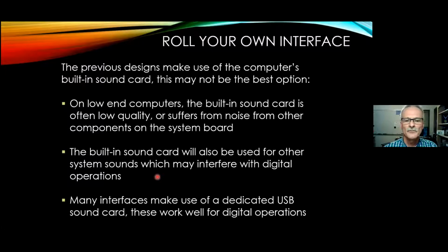So you have to be very careful, if you're going to use a built-in sound card, that you disable all system sounds from the operating system point of view, and also that you make sure you're not streaming any YouTube videos or anything like that, because you're going to be transmitting that sound out off of whatever frequency your radio is dialed up to.